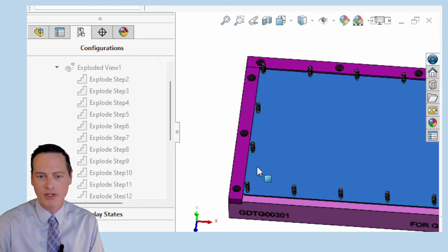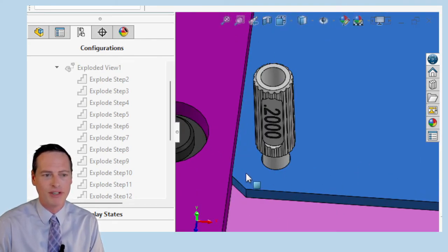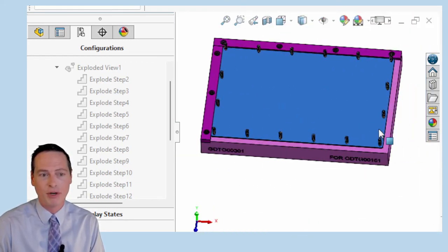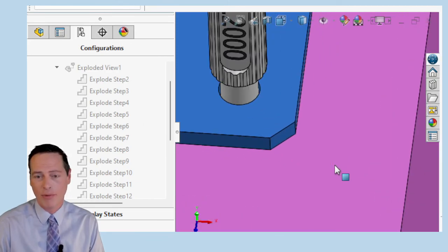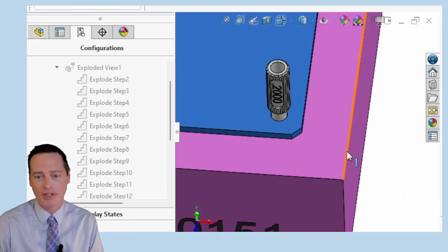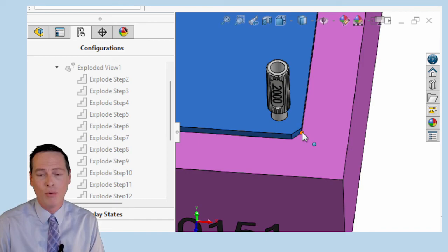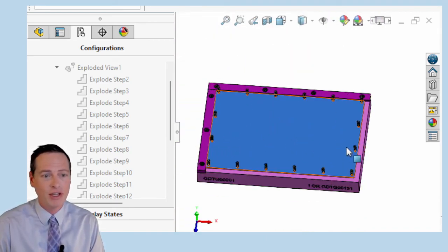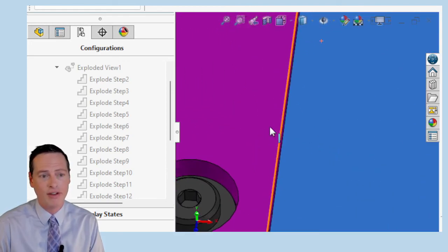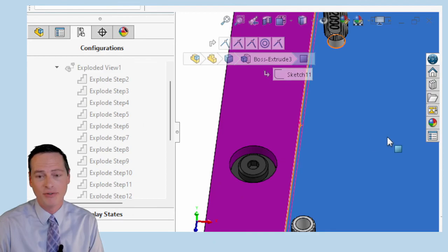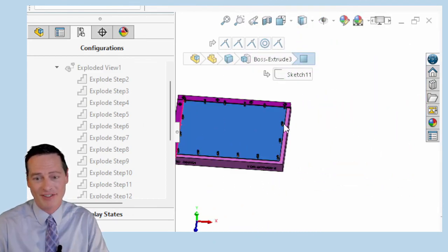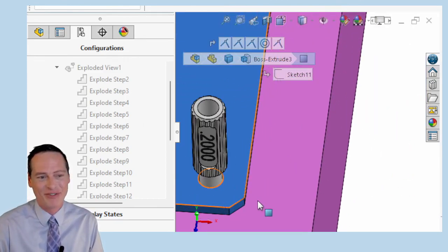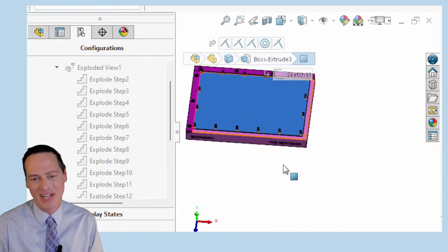Let's say it's pushing it as far as the 10 thousandths perpendicularity, and it's got a little 10 thousandths gap in here. And then it's also pushing it on the overall length of the part. It's up near 17.92. Well, in datum reference frame ABC, could that little corner out there be sticking out farther than 17.92 from the datum C simulator? Yes, it could be 17.93. Still, you can have a good part.